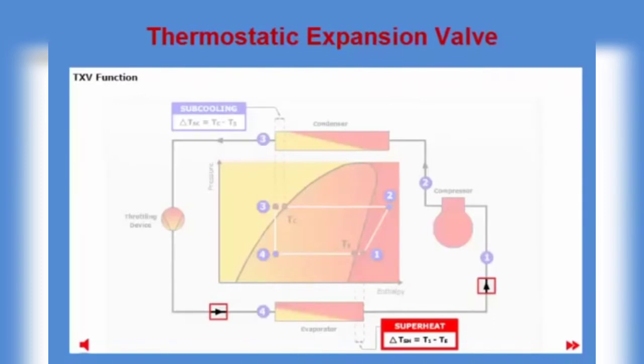Because the compressor can be damaged if liquid enters it through the suction connector, it's important to always maintain a certain minimum level of superheat in front of the compressor. The simplest way of doing this is to use a fixed throttling device, such as a capillary tube. This is typically done in, for example, household refrigerators and in other simple systems where optimization is not a selling point. A fixed throttling device can, however, only be effective for one set of operating conditions.